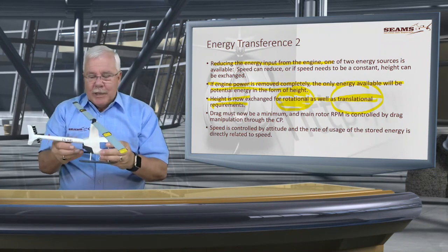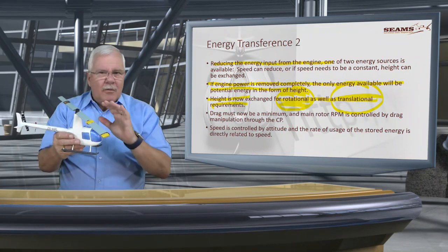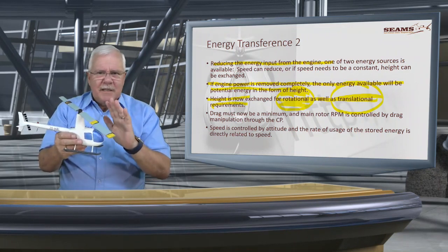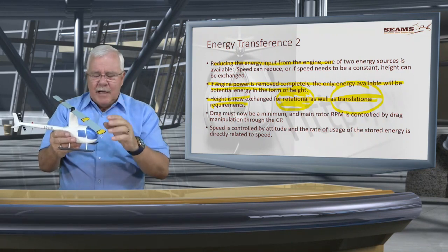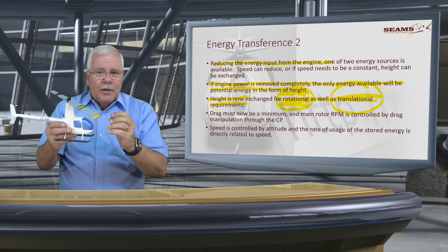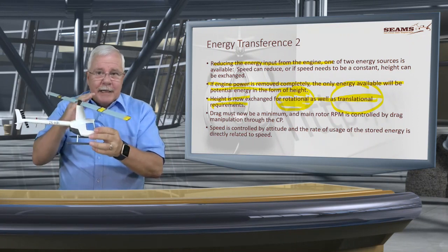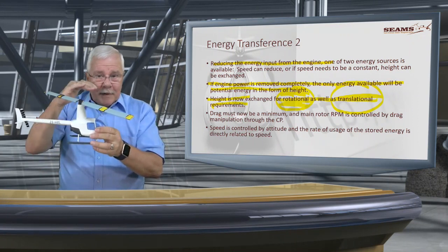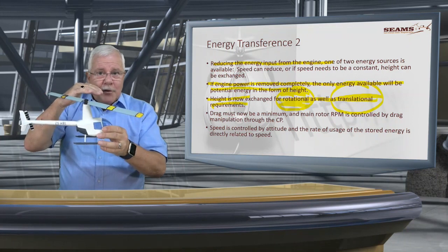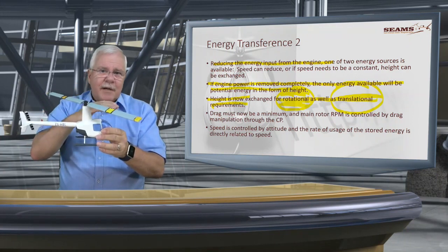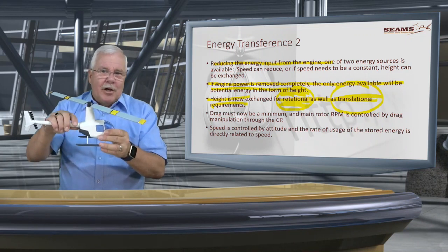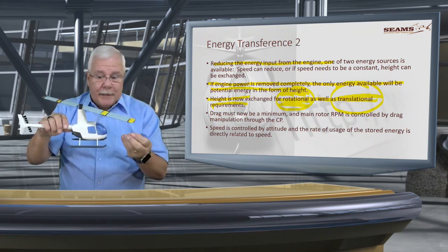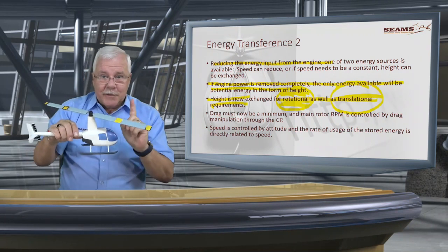And you will learn later on that for all helicopters, around about 70, 65, 60 knots is the autorotation speed. And normally you will have then flare effects, and you can manipulate flare until around about 40 knots. Below 40 knots, the flare effect is going to be minimal or none, depending on the design. So just think of that.